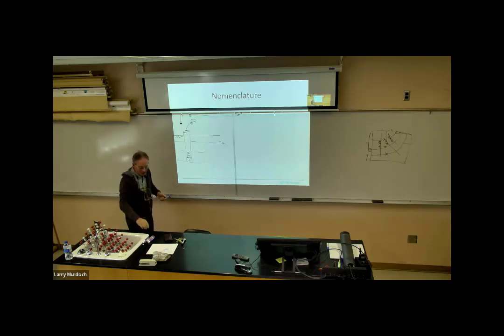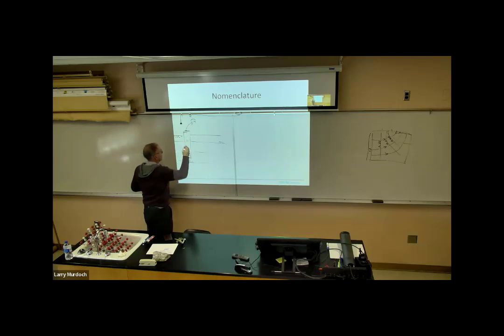Now, what that's going to do is cause the water level in the well to drop. And then we've got a gradient between the hydraulic head in the aquifer and the hydraulic head in the well. So the hydraulic head in the aquifer then is going to look like this. So it's dropping by that much.